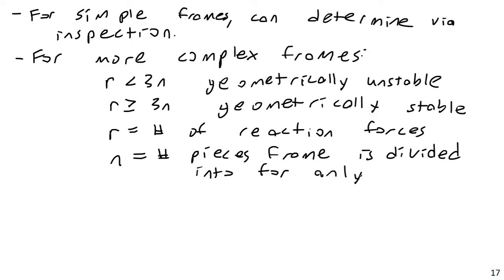And I thought I would give one note on this whole division thing. After class, a student came up and asked me about this one particular case, and I think it is a good practice, and something I should probably note. When you're determining your number of supports, your number of pieces and your number of reactions, if there is any kind of internal pin present in a frame, so for example, say we had a frame something like this. Say I had a pin there, and maybe a fixed support, and let's call a pin support here just for fun.